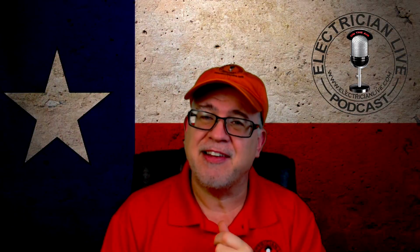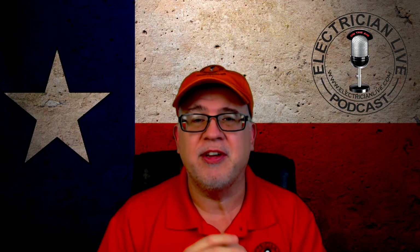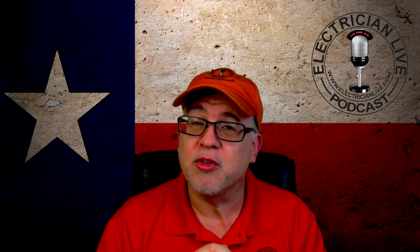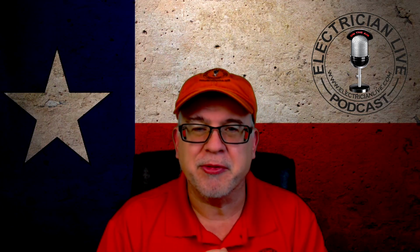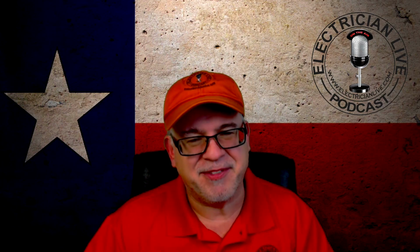Okay? So hopefully you got something out of today's lesson where we looked at 210.8(A) and kind of looked at the scope of what GFCI requirements are. You kind of understand now that the 15 and 20 amp threshold is gone. Okay? 125 through 250 volt rated receptacles, where it was 150 volts or less to ground, are going to require ground-fault circuit-interrupter protection in accordance with 210.8(A).